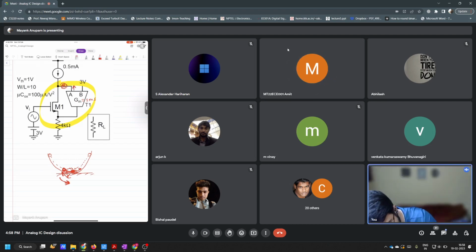So the voltage at this point is increasing, and let's say this is minus. I select randomly, and I will check if this selection is not correct. Let's say terminal A is minus and terminal B is plus. I choose this as a random choice. If because of this choice the system turns out to be positive feedback, then I will simply swap this, right? I'll simply change this. So this is one of my choices: A is negative and B is positive. In that case, I apply an input which is increasing at the A terminal.